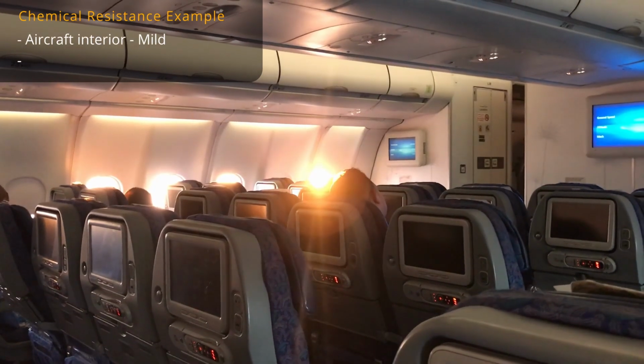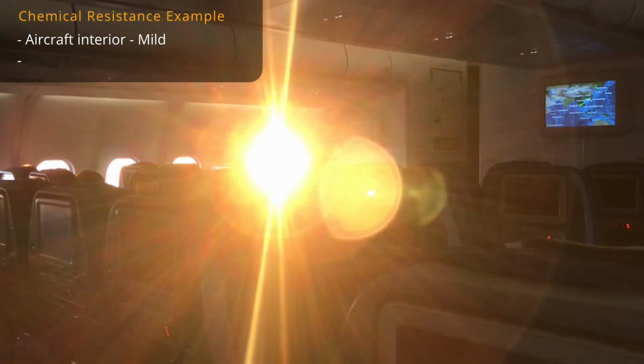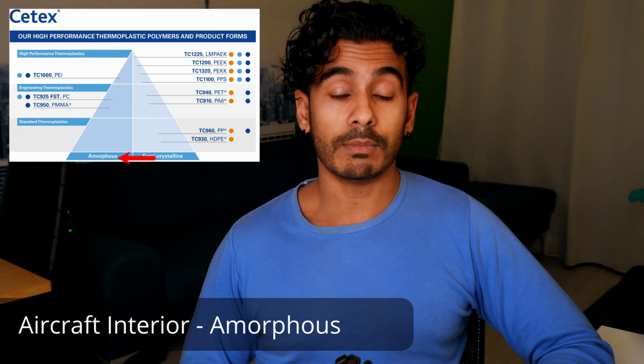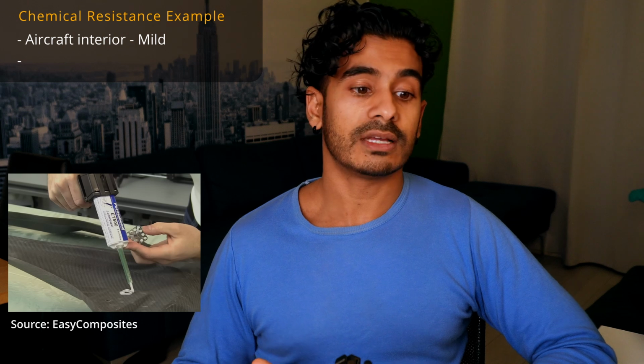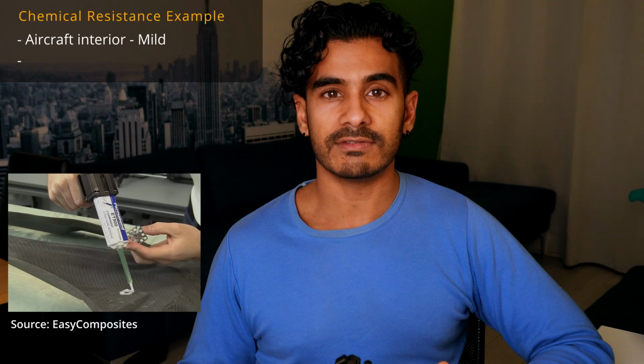So if you look at an aircraft, for the interior of the aircraft, this is an environment which is not exposed to a lot of harsh chemicals. So you have humans in there, therefore the most that you will see will be cleaning agents, which are pretty mild. And amorphous materials are very well suited for that. But also what is really good about interiors is, if you were to use amorphous materials, you could actually adhesive bond these materials very easily compared to bonding semi-crystallines or thermosets, which are quite difficult to use adhesives.